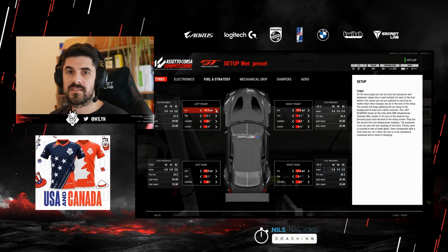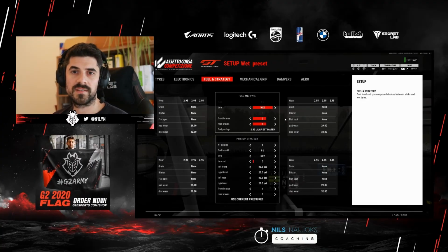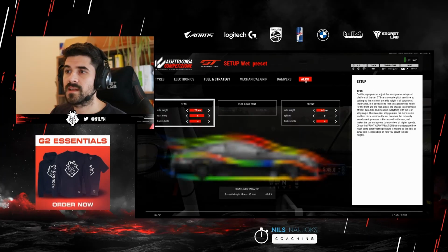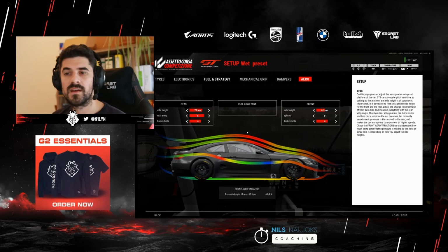So a lot of testing is involved to really get this right for wet or rainy races. Another thing in the rain is that temperature has the same importance, but in the rain we're always looking at rather more cooling conditions. We can go back to our aero tab and think about the brake ducts in a different way, because they could be helping us generate heat in the tire and also keep the brakes up to temperature so they work a tiny bit better in these conditions.